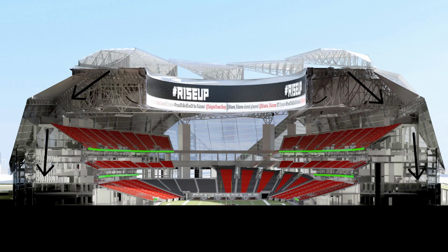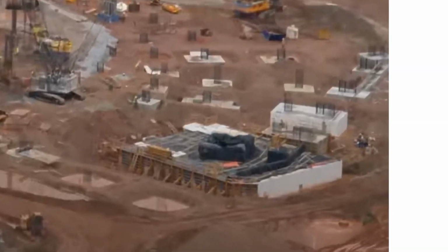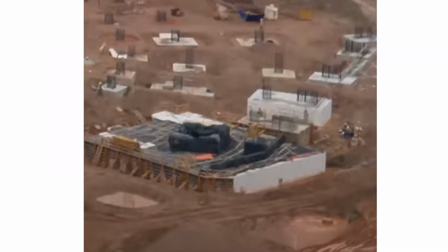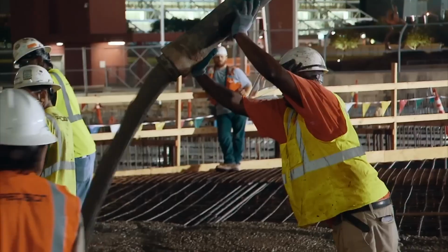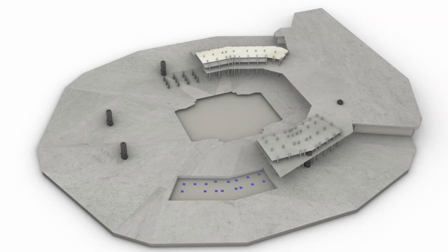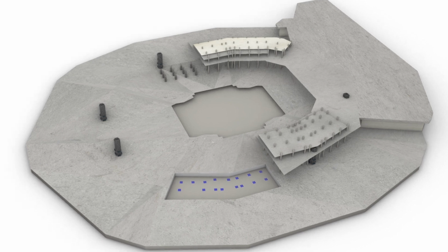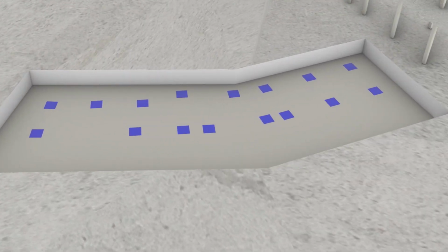Due to the massive roof truss system and lateral structure, Mercedes-Benz Stadium concentrates structural and lateral loads on specific key points. To safely resist these forces, the project adopted a thick high-strength mat foundation and installed 19 mega columns instead of conventional spread footings. This foundation system was chosen to distribute large axial and moment forces, particularly around column zones where reinforcement density was increased to prevent localized failure and settlement.